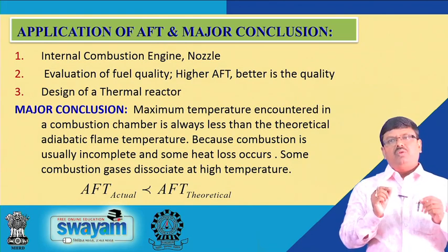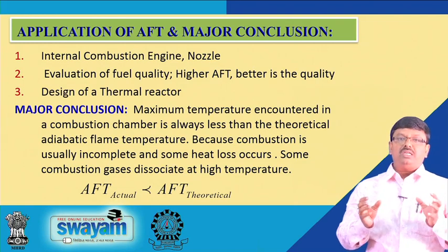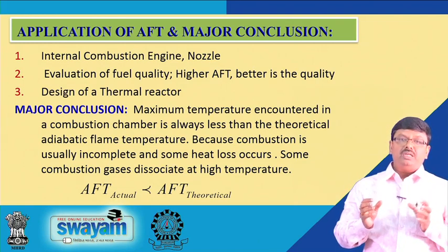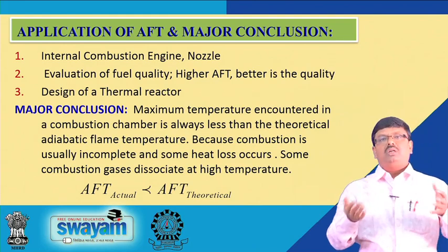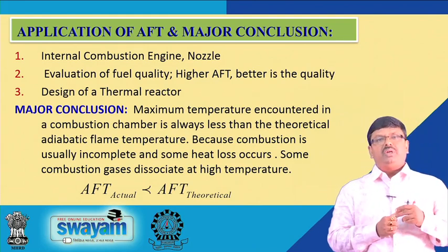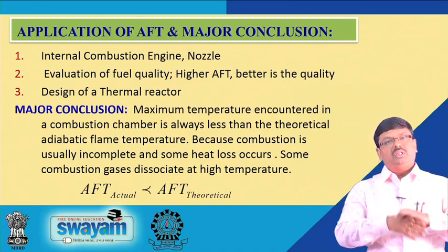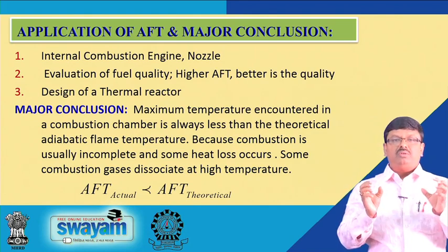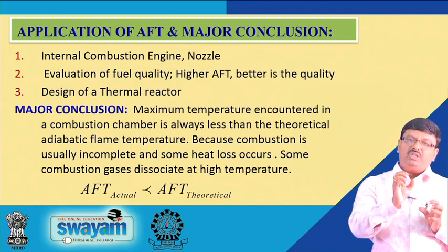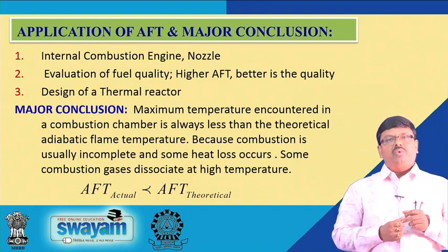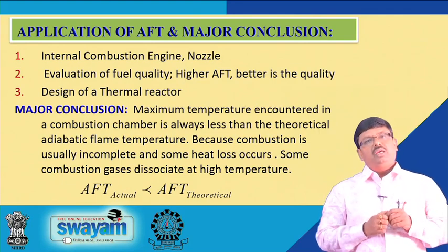What material should be recommended by the chemical engineer, the process engineer or the furnace engineer depends on the process taking place inside, and the temperature, how high it can go, and the materials we can consider which can tolerate this temperature. So, this is what we generally do when considering this AFT.